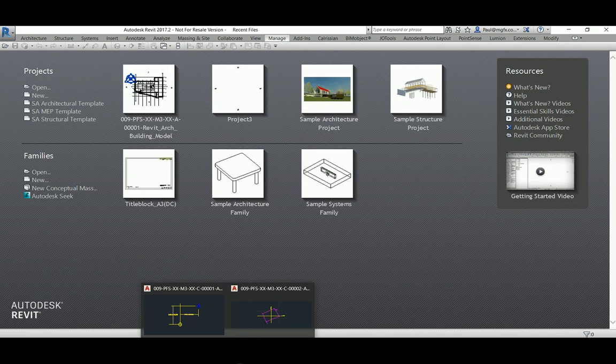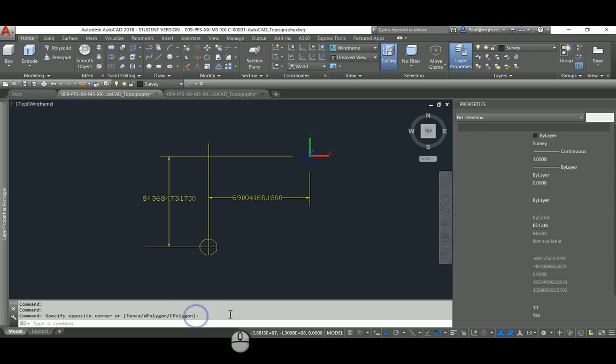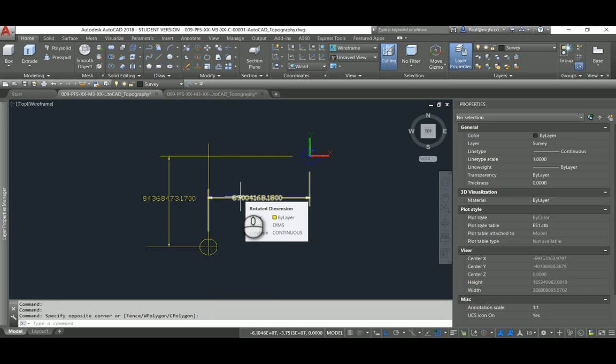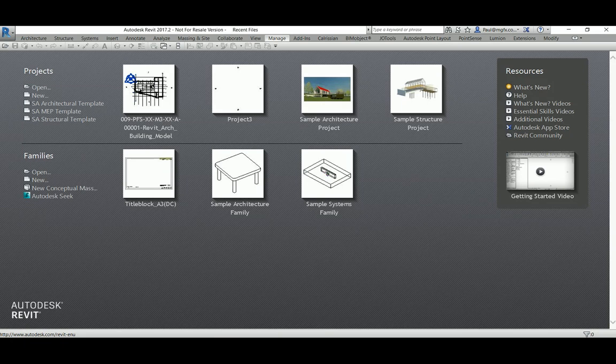Partly the reason is because Revit does not handle creating geometry far away from the origin very easily. It really doesn't like things that are further than a mile, or even 20 miles for that matter, and this is a little bit further than that. On the other hand, I've drawn the solar system to scale in AutoCAD with really great results. So AutoCAD and Revit, really two different beasts. Revit doesn't handle distances very well at all.